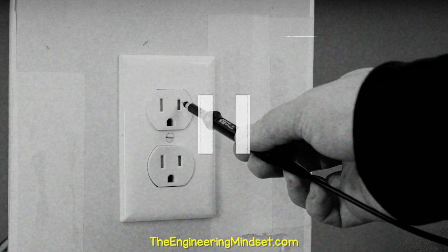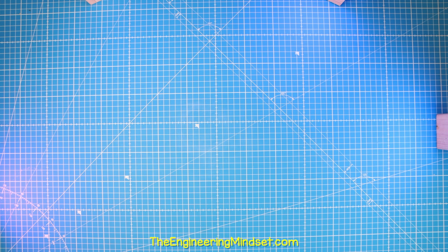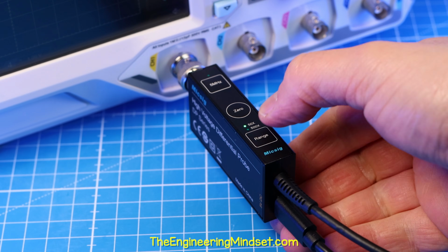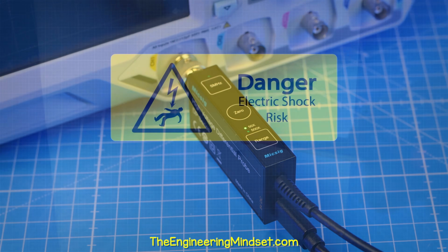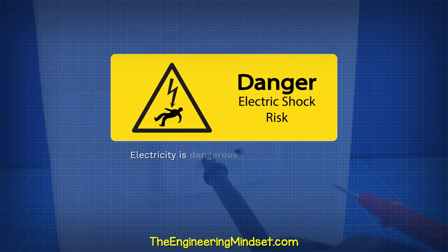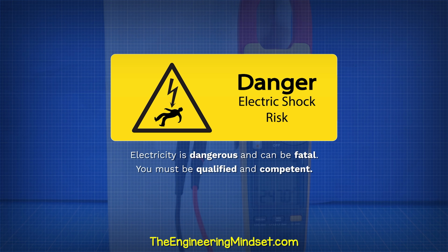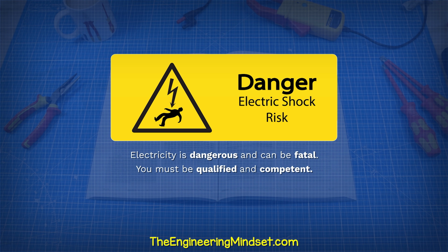If you must connect to a mains AC circuit, you should use a differential probe set like this, which isolates the circuit from your device. But remember, electricity is dangerous and can be fatal. You must be qualified and competent to carry out any electrical work.